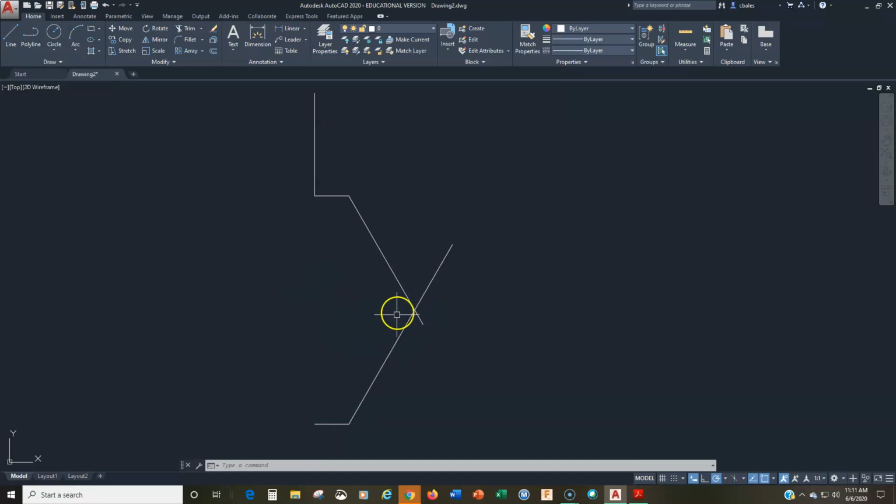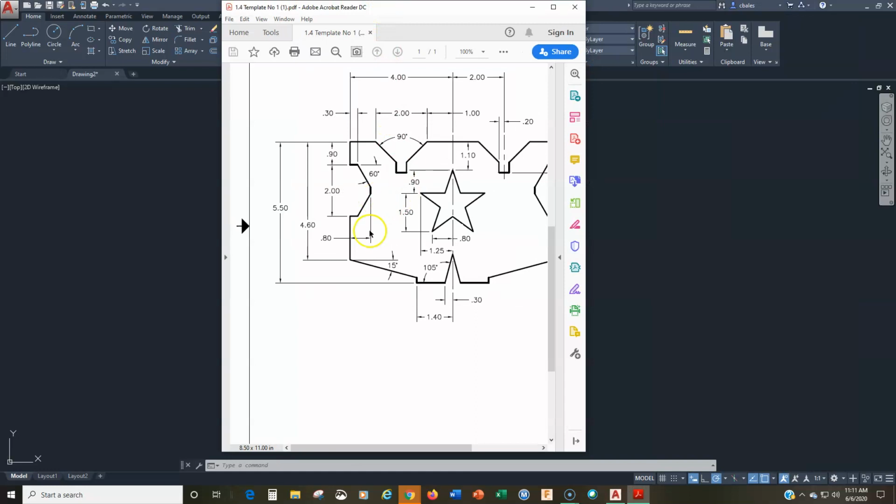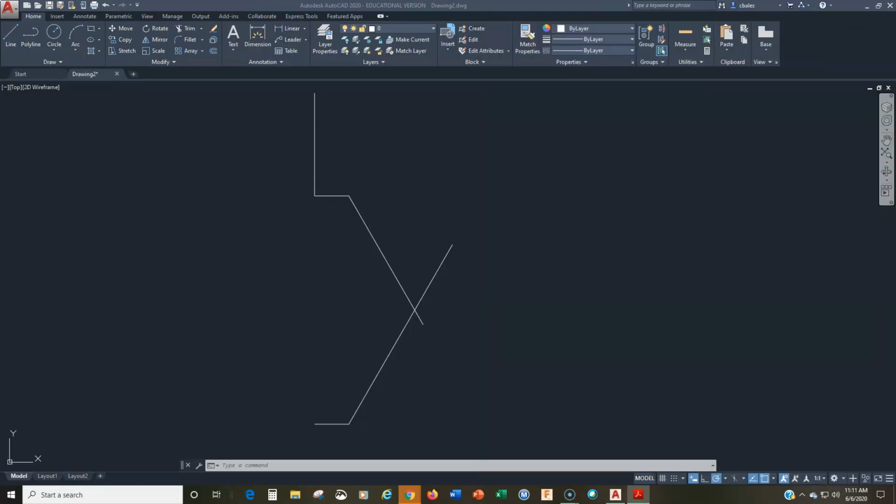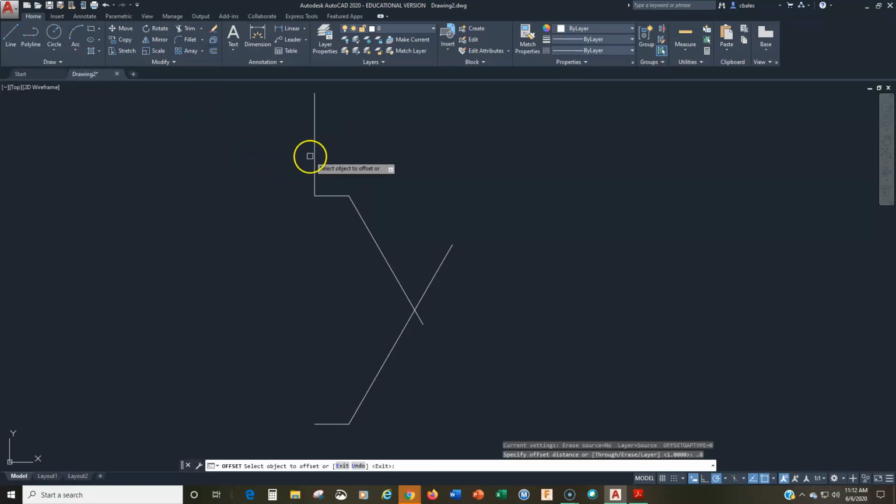All right, so now let's rejoin. We have to get the back surface over here. So, hey, you know what? I'm going to do the same thing because, look, I got this distance right there. This distance, 0.8, from this edge over here. So what could I do here? Now, there's a couple of things that we could do, and I'm going to show you both of them, and I'll let you choose which way you go. They both use commands that we have already been exposed to. So one is just to use the offset command. Offset. 0.8, take this line and offset it right there.